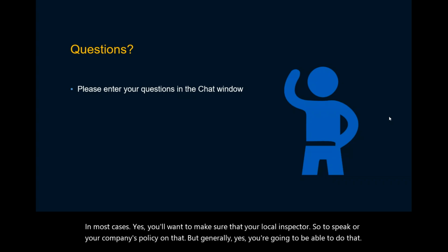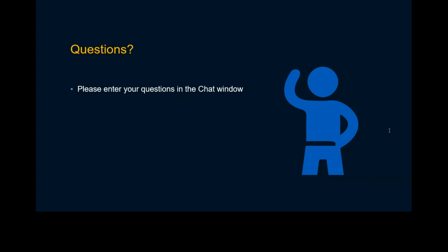Okay, and the last two. The first one is, on a 2-wire device, if I use an IS barrier, does that meet Class 1 Div 1 requirements? And that also has a statement in there saying, explain that the transmitter must be IS, as some devices like a capacitor can store energy and thereby cause a spark. So the transmitter must also be IS certified, and one must look at the entity approvals of the barrier and the transmitter to be in compliance.